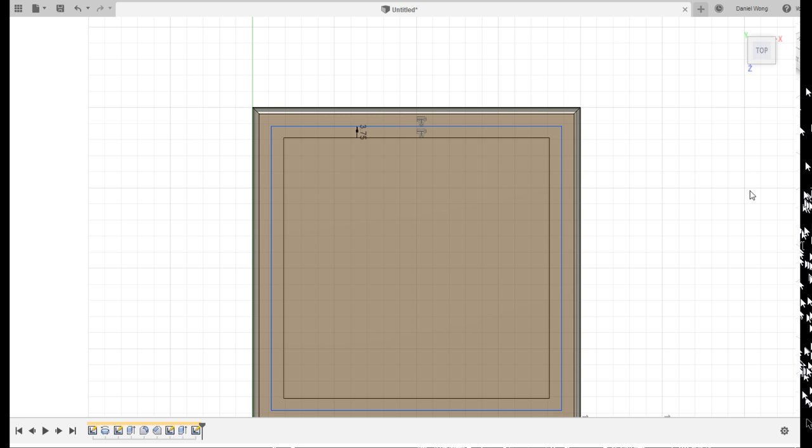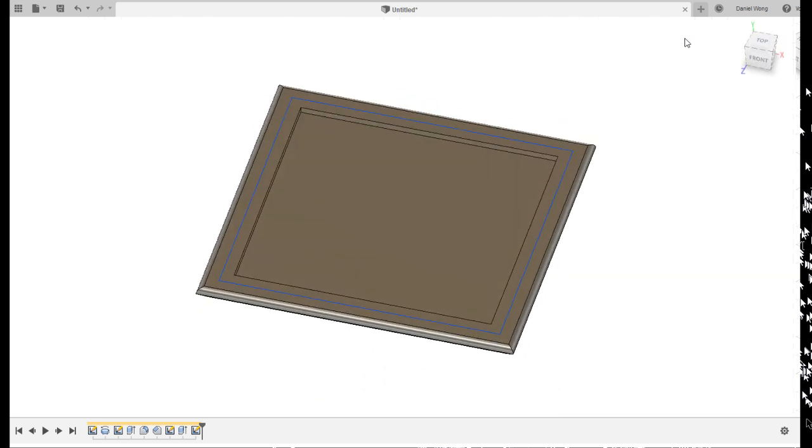So we've defined the path that our thing travels around, the path that we're going to be cutting along to make our little recess to rest our hands on. But the other thing we need is the actual cut that we're going to make along that path. What's challenging about that is, where do I put the sketch that I wish to cut it along? What's important is that that sketch must touch in some way this line here, because otherwise it's not going to be able to extend that along the path.